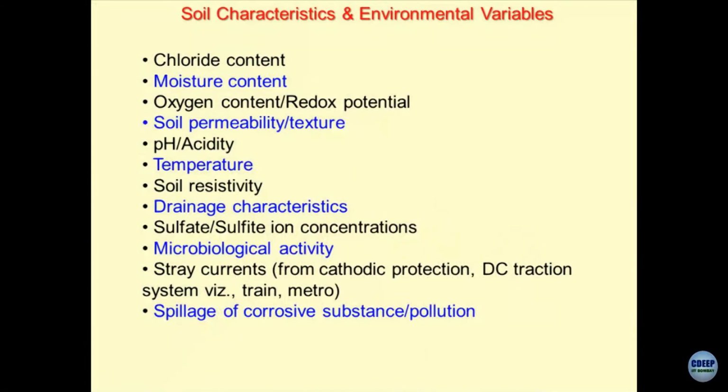pH and acidity of the soils is also a big question, how the soils will behave, because pH is a parameter which controls the bacterial activity quite a lot. So, a drop in pH of the soils or the backfill covers which are being used even for placing the foundations matters. What do you do in shallow foundations? You dig a pit, place the foundation, cast the foundation, and then cover it and compact it. Imagine if you are using soils of very low pH values or very high pH values, it is not going to be good for the health of the buried structure. This type of thinking was not done in the past, and hence it is becoming very important now.